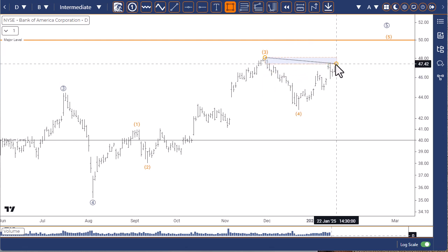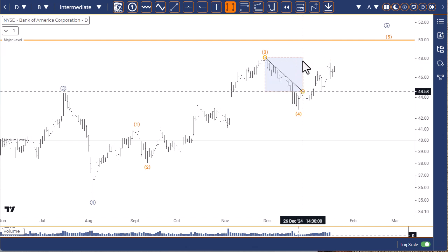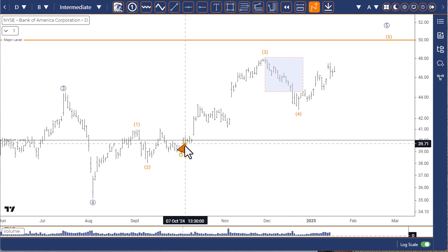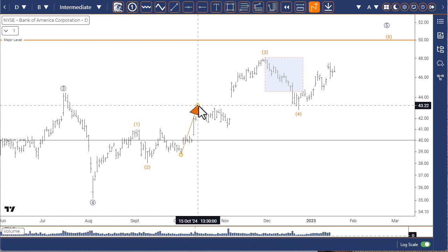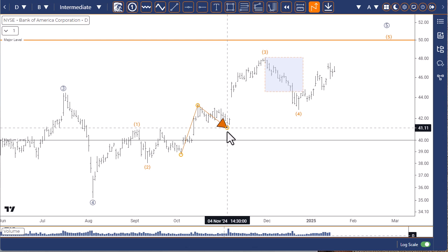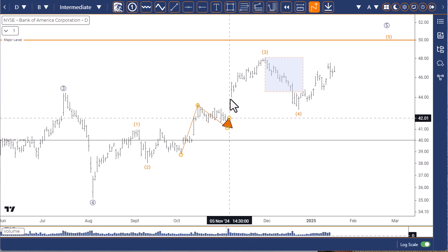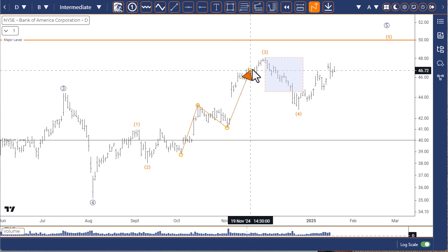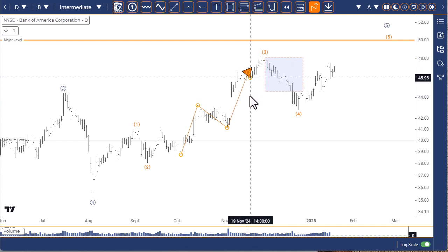Then you can move it wherever you need to move it to at that particular point, so it moves freely like that. This will be the same as this one here as well. Sometimes it just jumps between that high and the low there, which is a really good thing, because then you can put things very accurately, but sometimes you don't want them to jump around. So you hold the control key and the shift key down on your keyboard, and then it doesn't jump around. You can move it to wherever you want. That's just the little trick with that.